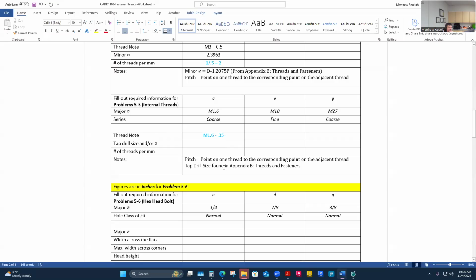And that's really all I can evaluate to, just 2 columns there. On that same chart, it probably does have the tap drill size, which is the drill size I would need if I was going to cut my own threads. This should be a much smaller diameter than the 1.6 in order to cut threads.